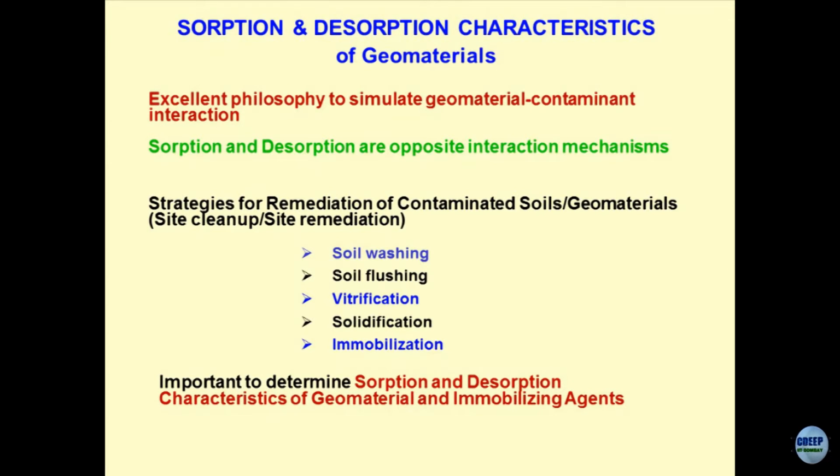This comes under the category of site cleanup and site remediation program, and there are several types of strategies for remediation of contaminated soils. The first one is soil washing. Alright, you inject fresh water into the soils which are contaminated, and then we presume that desorption process will occur. The contaminants will get released from the substrate, they will flush out in the pore fluid, and this pore fluid can be sucked out later on. Is this okay? This is what you have been asking.